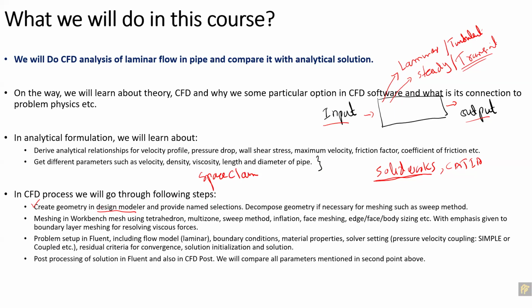Their important use is that they are basically used for correcting geometry. When you import geometrical models like CAD models, they have some errors, not errors in the geometry, but from the CFD point of view: different surfaces are not connected, there are gaps, overlapping surfaces, maybe extra edges. For example, this is a very simple geometry. It might have a hole here, a gap here, so you have to fill this gap.